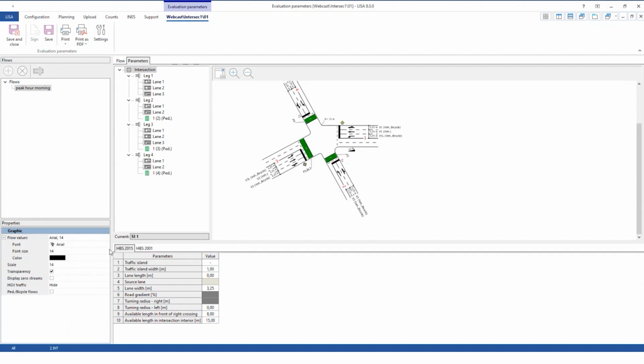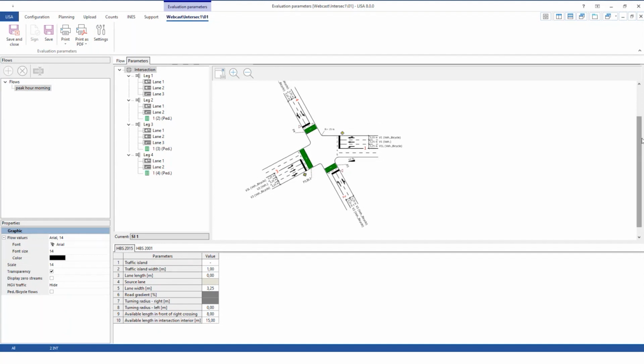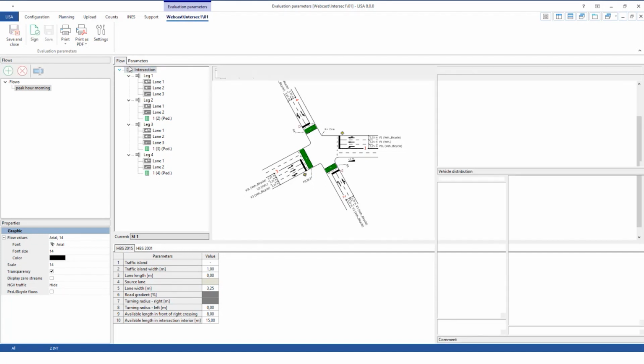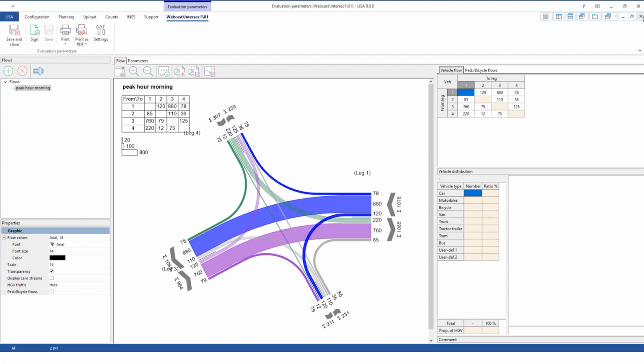that will then influence the capacity calculation based on the German roadside manual. The German roadside manual basically works, all the quality measurements are based on waiting time. So you usually end up with quality or levels of service from A to F. And behind every level of service, there's a certain waiting time threshold. So everything below a waiting time of, I think, 25 seconds on average is A, waiting times higher are B, and so on. There's a threshold for every level of service. And all this is based on the geometry and of course on the number of vehicles and the green time.